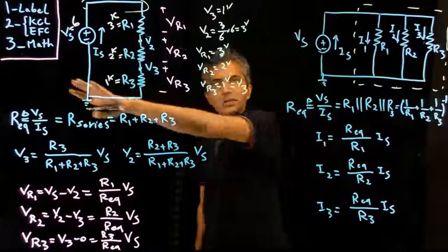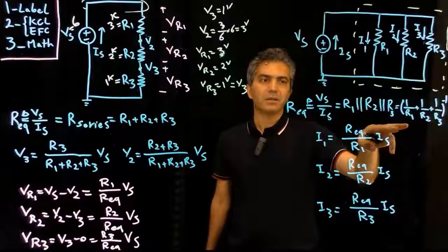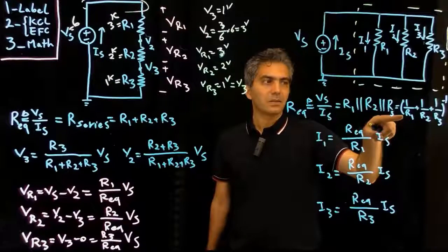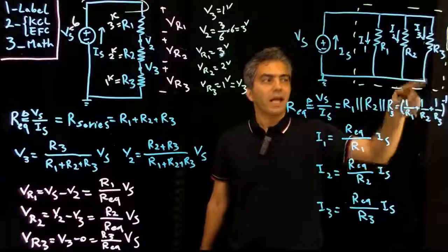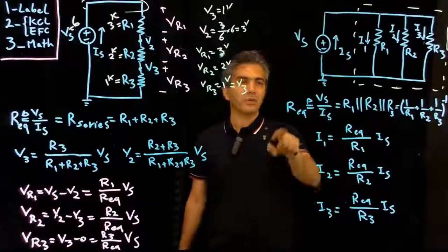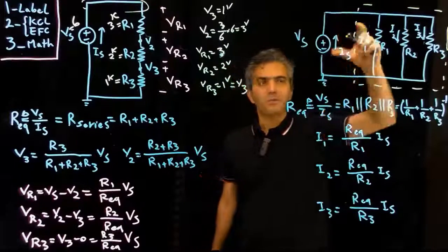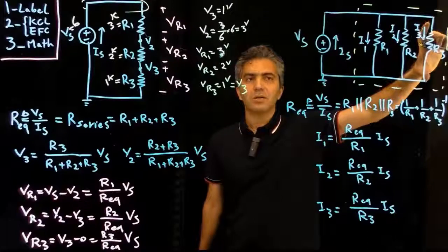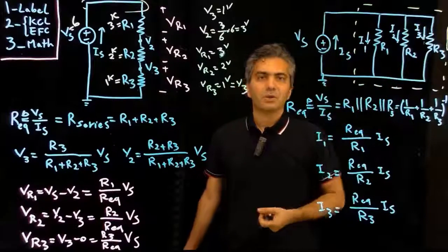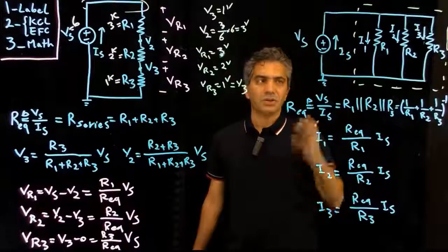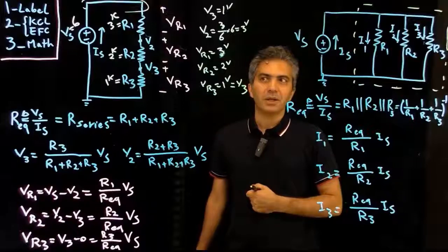Now, we did the calculation, again, using the same algorithm, and we calculated the equivalent resistance, and in this case, it was the inverse of each resistor added up by each other, and then the whole thing inversed, and that would be the equivalent resistance. Now, obviously, the voltage across each one of these resistors is going to be the same as the voltage that you connected. That's by definition how you put the components in parallel to each other.